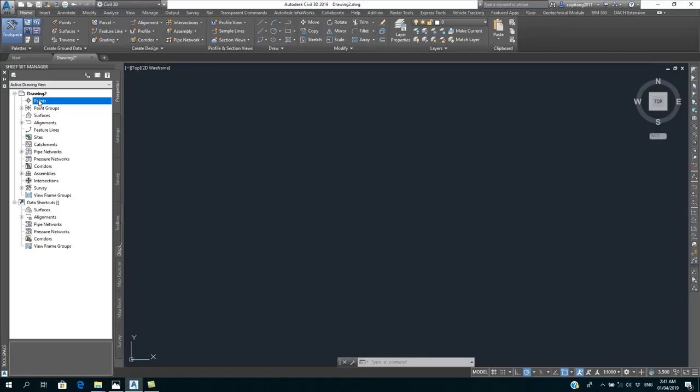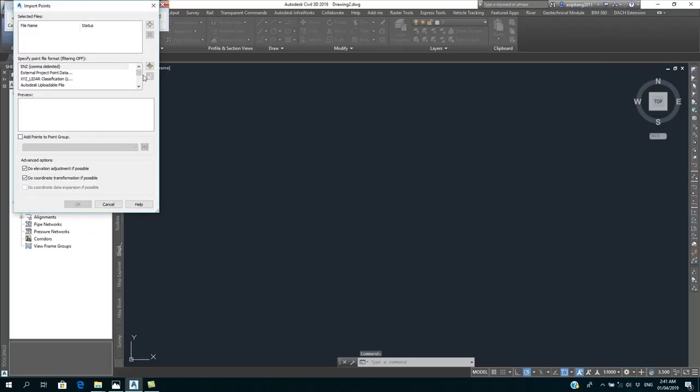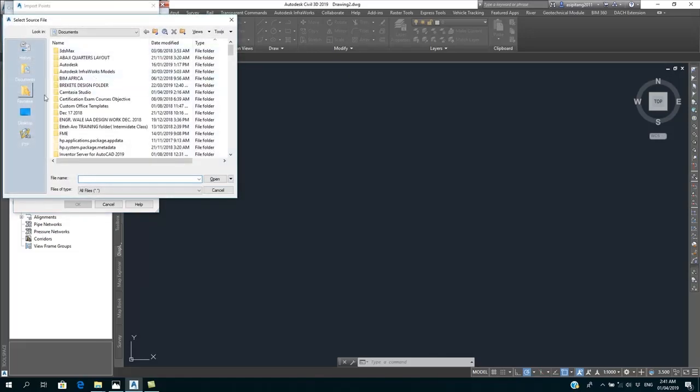So we still have more to go. So let's continue. We're working directly with the survey data. I click on create data. The next is I want to import data. In most cases, you already have the established survey data. I click on it. Next, I go to the particular format that it will save. Select the format, space delimited, or import the data. The data I import is an Excel file, saved as a .csv file.